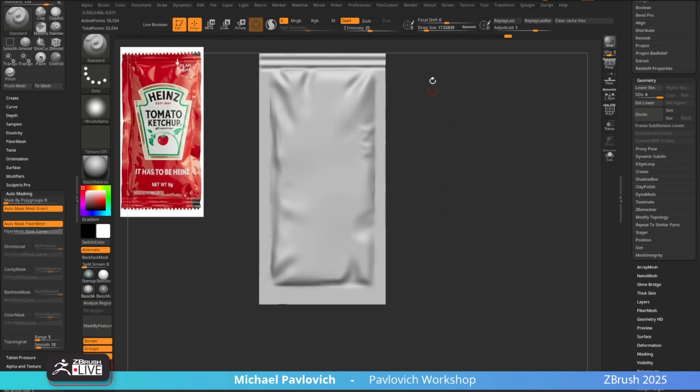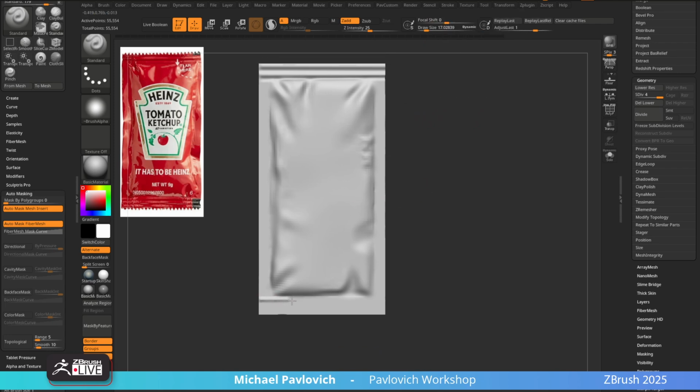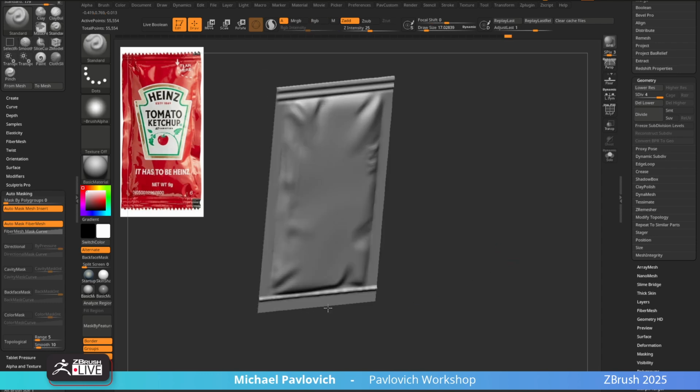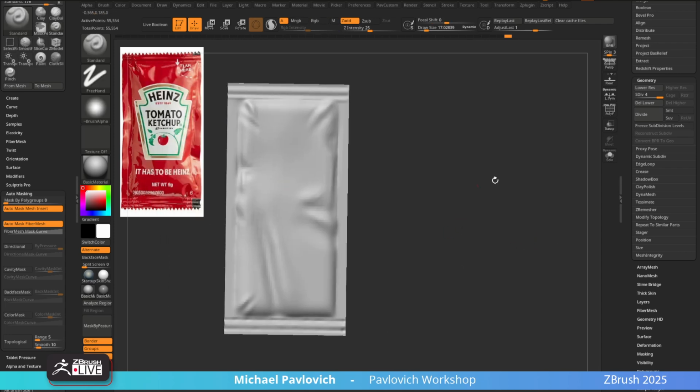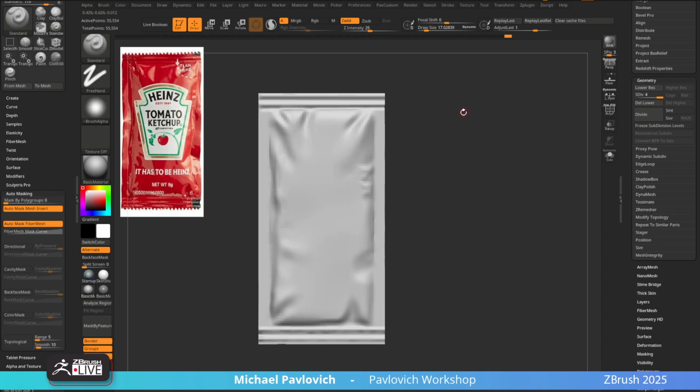Now, if I go in here to stroke and tap L, lazy mouse off, as you start sculpting, you just hold down Shift, and it'll constrain you to a straight line. It's a little lumpy. Let me see. Can I try lazy mouse dot, freehand maybe? Can that even this out a little bit? Not really. It's not terrible, maybe not great, but you can constrain your stroke, and you can do that. So that's fine. Use those to your advantage if you'd like.